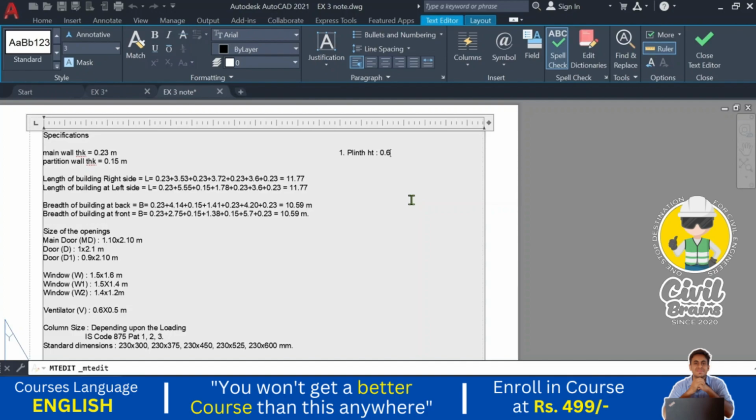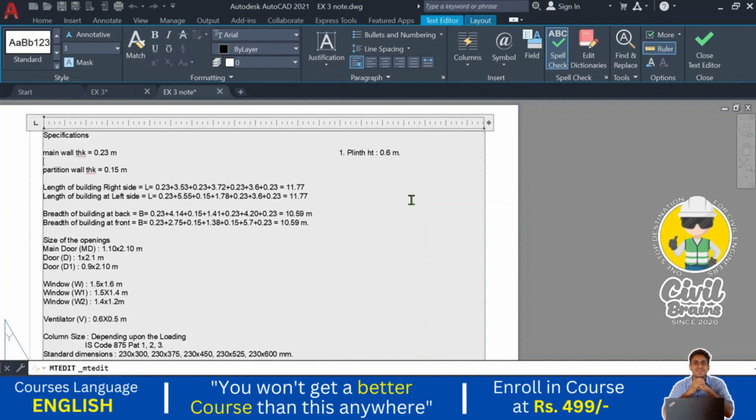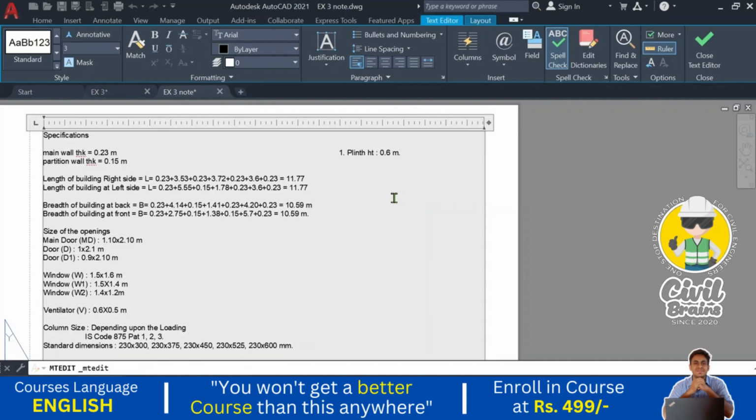0.6. We have taken 0.6 meters. Okay, so why have we taken 0.6 meters? The plinth height depends upon the water table and upon the road levels. The water table is a little high here. In the rainy season also there is a chance of water being present.